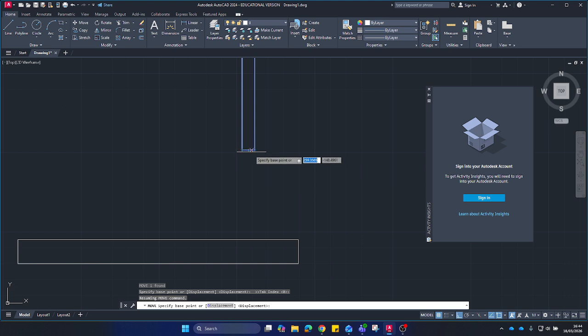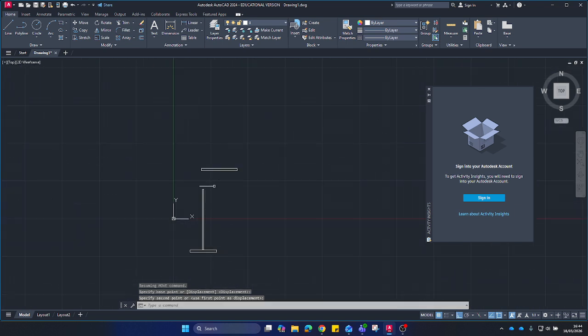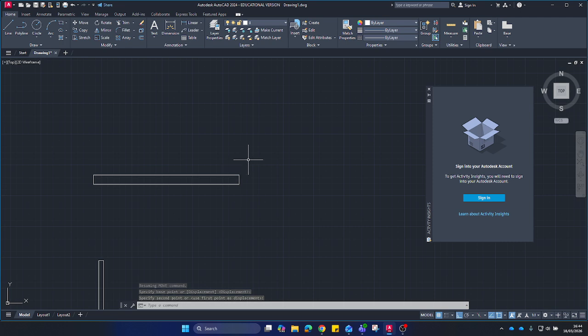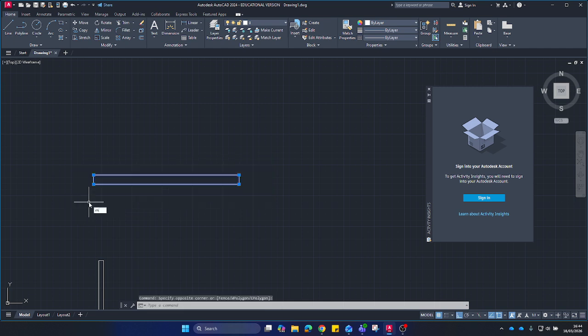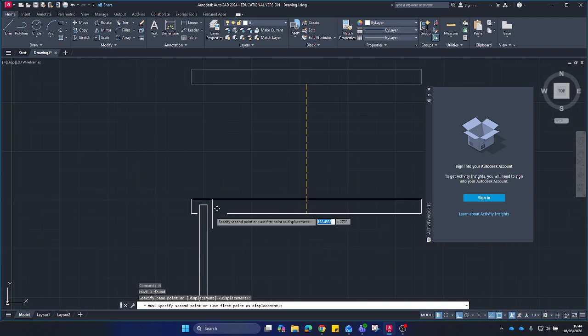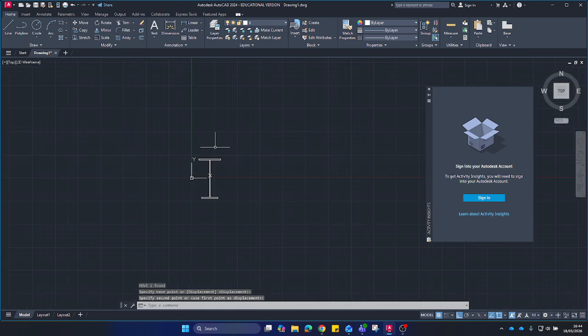Therefore, I can snap onto the middle. It goes to a little green triangle. To the end, it goes to a green rectangle. I'll go back to the middle, and then snap there. Nice and easy. Then I'm now going to select this top element. I'm going to right click just the once, and drag, draw a rectangle over to the left, click, as it's selected, press M for move, enter, I'll snap to the middle, I'll zoom right in with the mouse, and snap to the middle again. I've now got my shape correct.